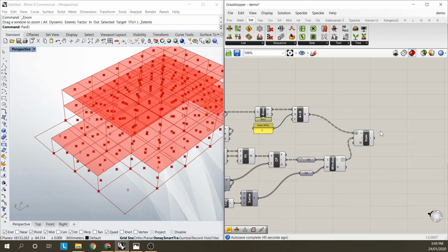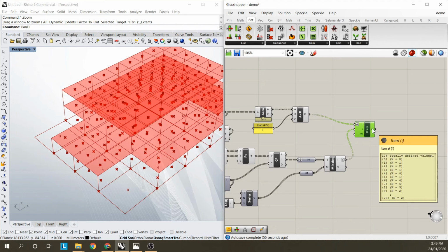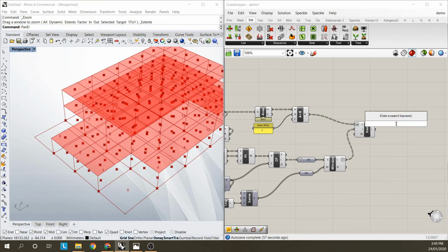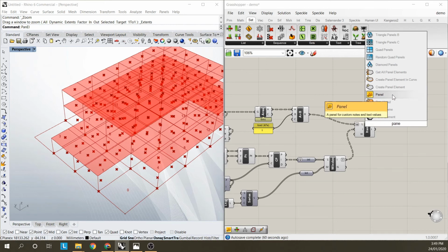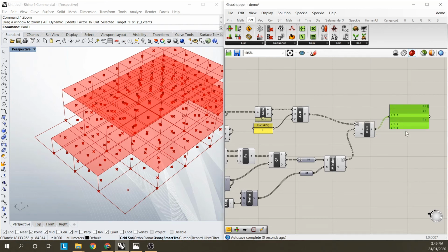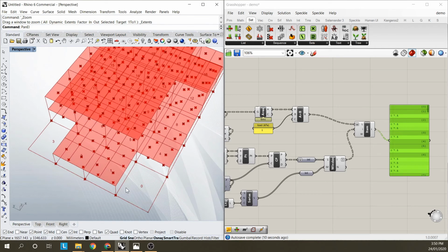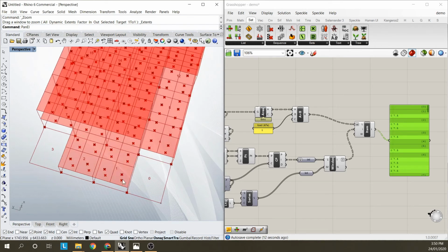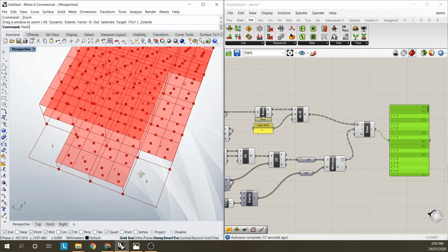Right, so next step is I've got all my loads now for each of these panels. So as I said before, actually I'll recreate that panel. For panel 0 I've got nothing. For panel 1 I've got 7.5 kilonewtons, or for column 1 I should say. So that's that panel there. For column 2 I've got 2 lots of 7.5. I've got that one and that one.